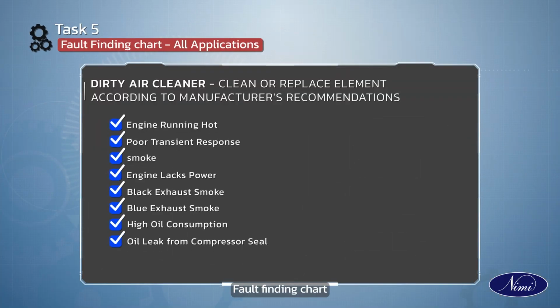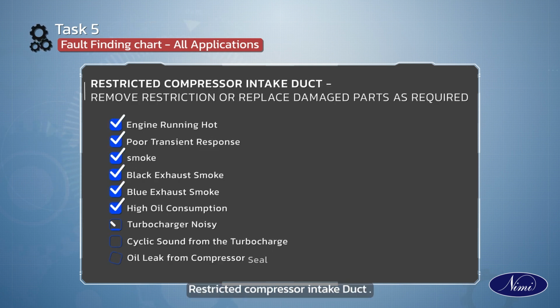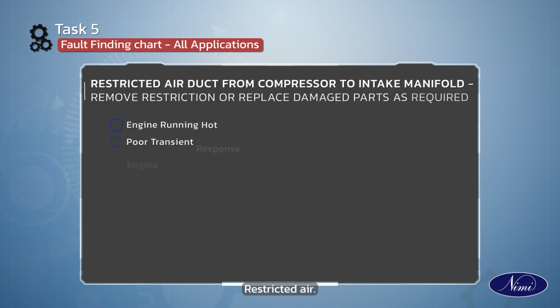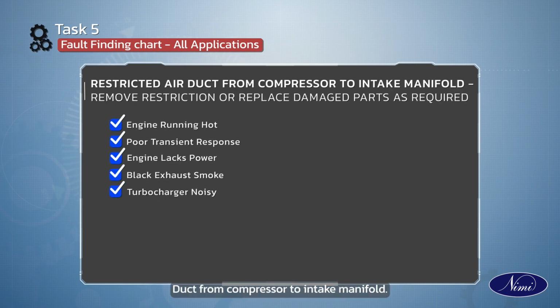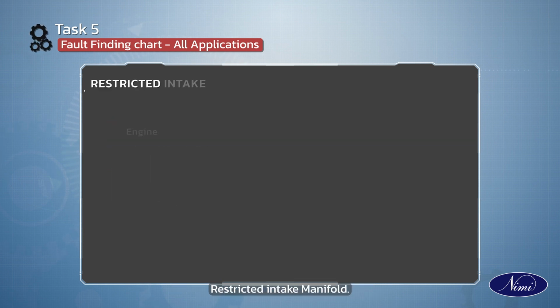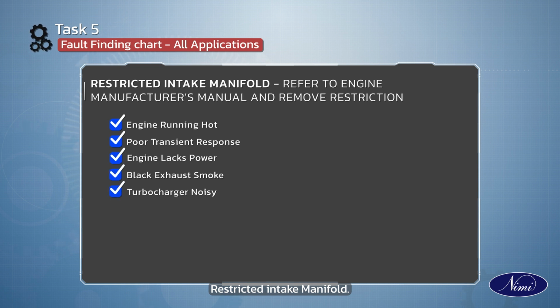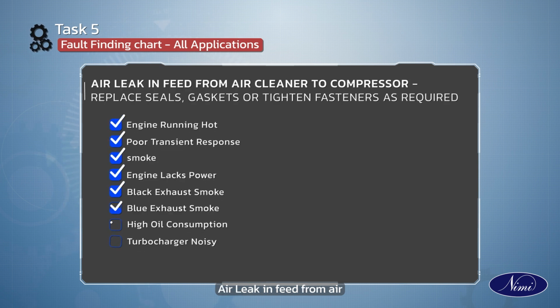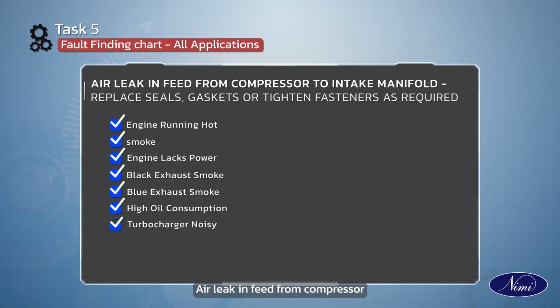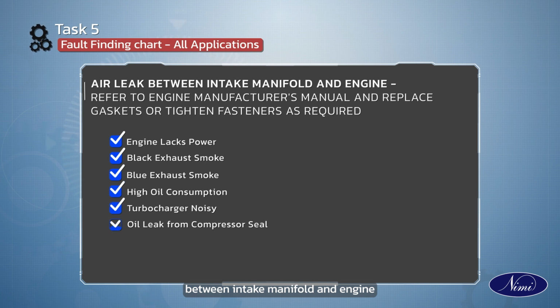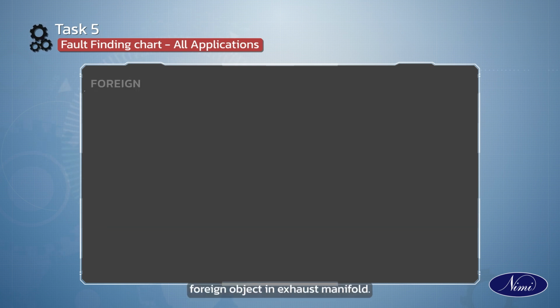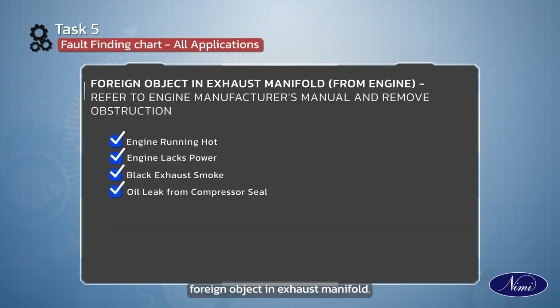Fault finding chart, all applications. Dirty air cleaner, restricted compressor intake duct, restricted air duct from compressor to intake manifold, restricted intake manifold, air leak in feed from air cleaner to compressor, air leak in feed from compressor to intake manifold, air leak between intake manifold and engine, foreign object in exhaust manifold,